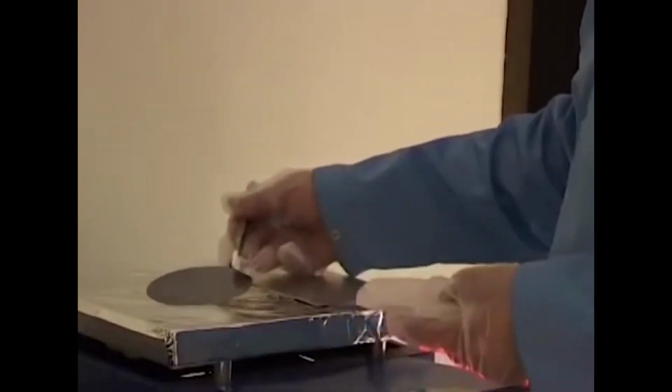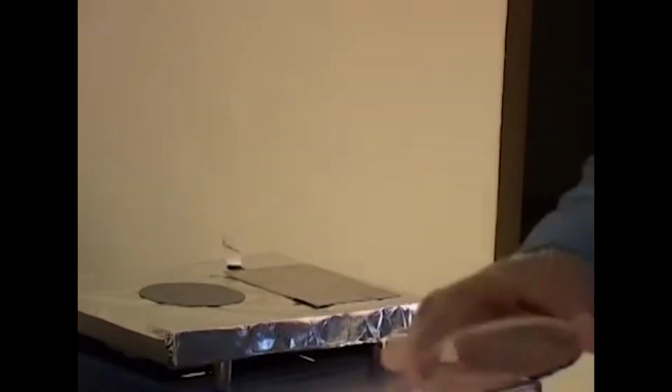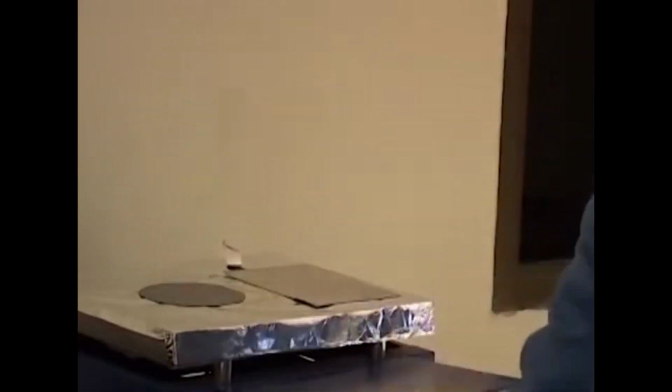Okay, so basically now we actually put it back onto this wafer surface, onto this hot plate surface, which is set at 95 degrees Celsius, and essentially we heat this for about 6 minutes or so. And one thing very good about this process is that if you look at closely, you could really see the features coming up on the surface as you are heating using this 95 degrees. Essentially the points which are